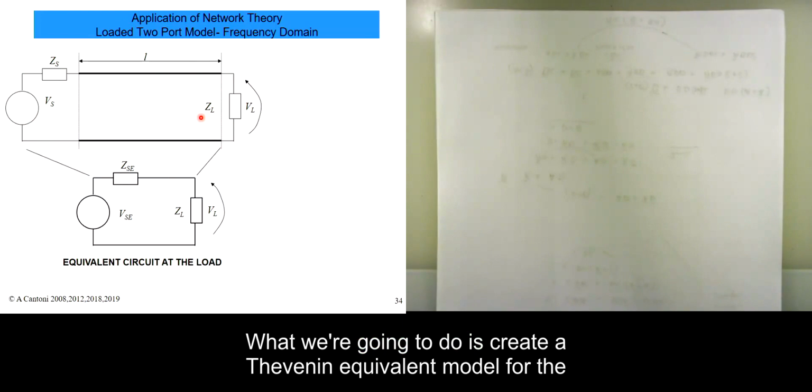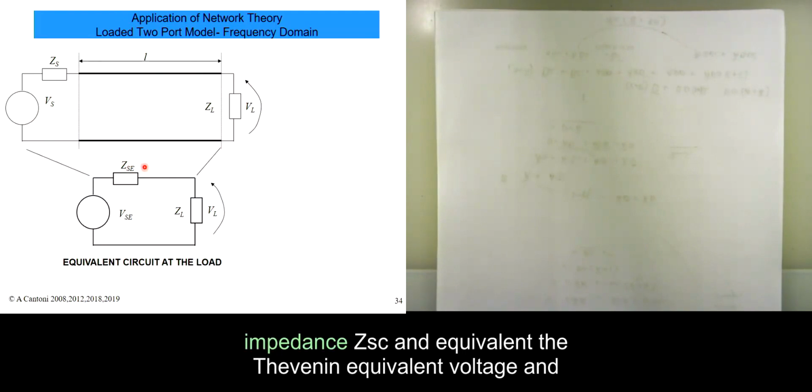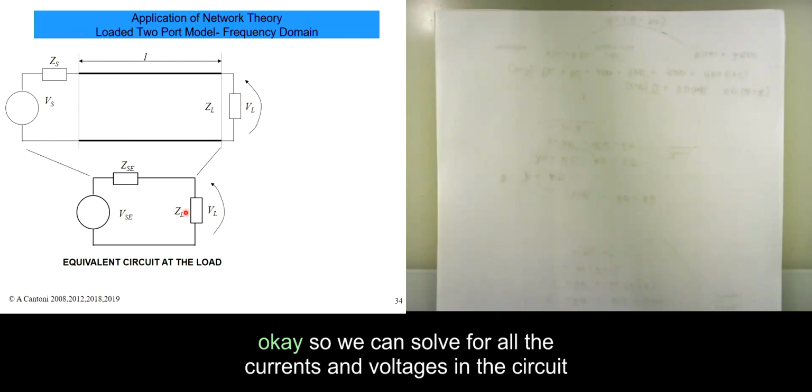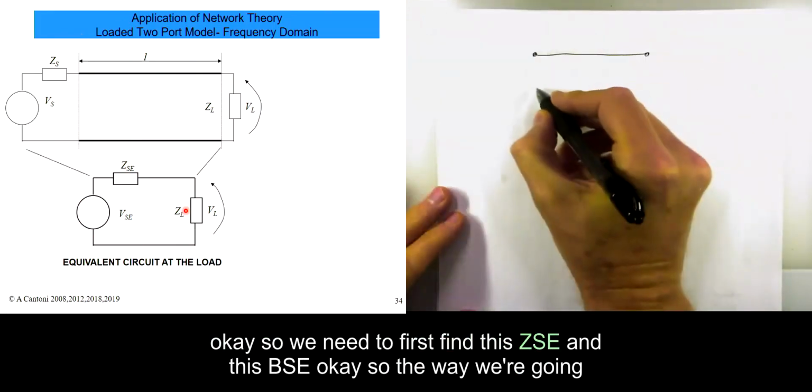What we're going to do is create a Thevenin equivalent model for the transmission line and the source. So we need to find this equivalent impedance, ZSC, and the Thevenin equivalent voltage, of that transmission line plus the real source. And then once we have that, we can just solve for any VL and IL at the load. So we can solve for all the currents and voltages in the circuit. So we need to first find this ZSC and this VSC.